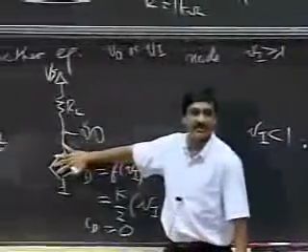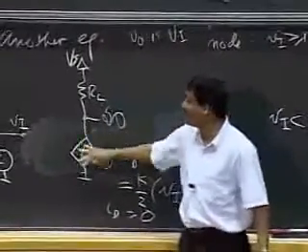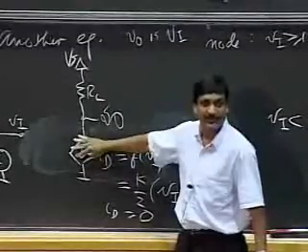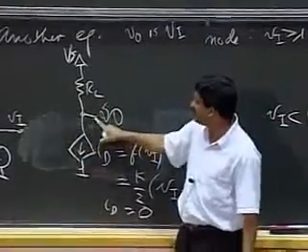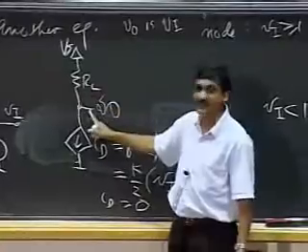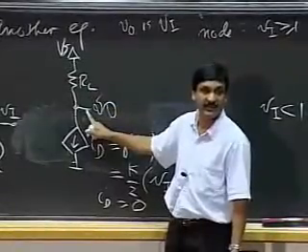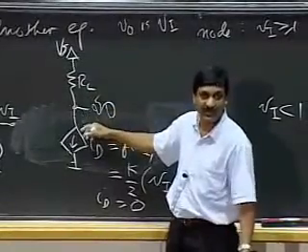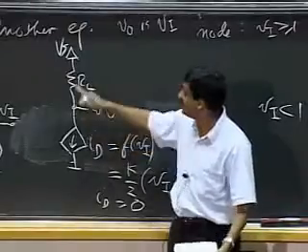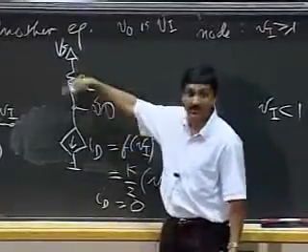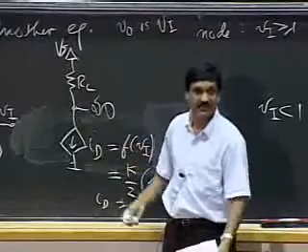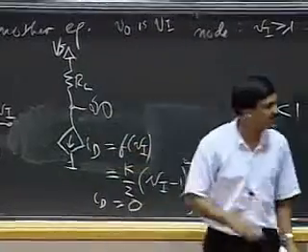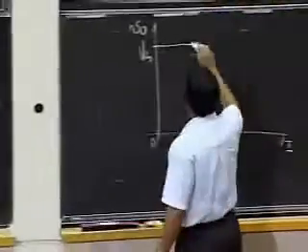As long as the current here is 0, this is like an open circuit here. If this is an open circuit, then effectively V0 is simply the voltage Vs. If you want to grunge through KVL and KCL, go ahead. Vs minus RL times the current is V0, and the current is 0, so it's Vs. So this is simply Vs.